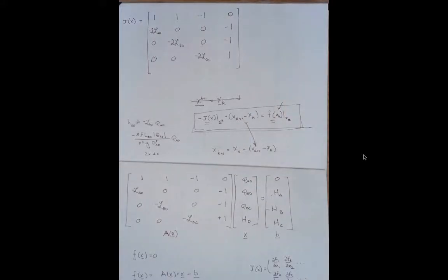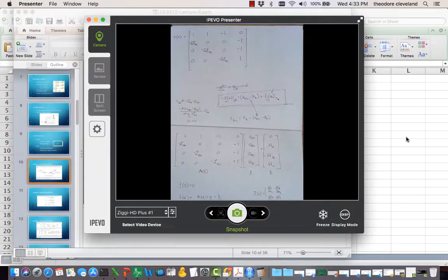So now we're going to build a spreadsheet model to handle the various parts of the calculations. We'll build it specific to this problem, but it will become reasonably obvious that it's expandable to any problem that can be structured in the hydraulic modeling sense, and that there's the correct amount of equations and nodes.